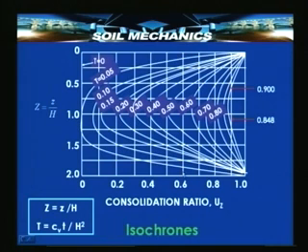Now, what you should pay attention to in this picture is that as time varies from roughly 0 to its maximum possible value, the pore pressure variation with depth, which is parabolic, becomes less and less in magnitude and less and less in curvature, and ultimately it becomes 0, and this is what the consolidation phenomenon is.